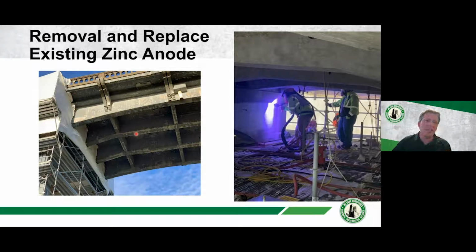It's pure speculation as to why that's the case, but it likely had something to do with the monitoring system and how the rectifier behaved in providing DC current over the lifetime of the structure. Some areas underwent more wetting and drying. The zinc got consumed more. Other areas were drier. The zinc didn't get consumed as much.